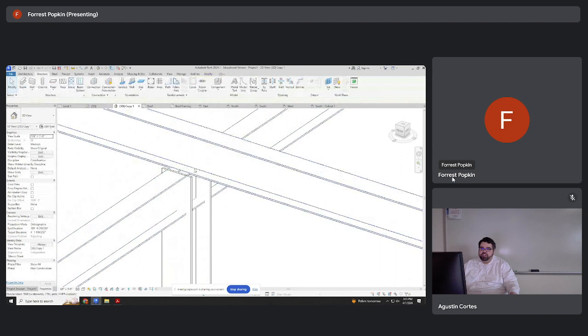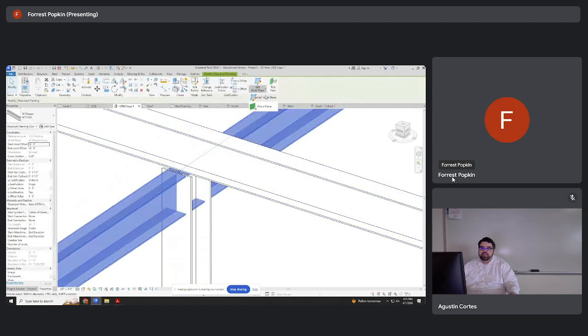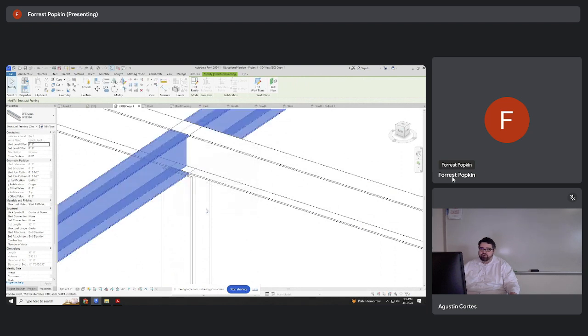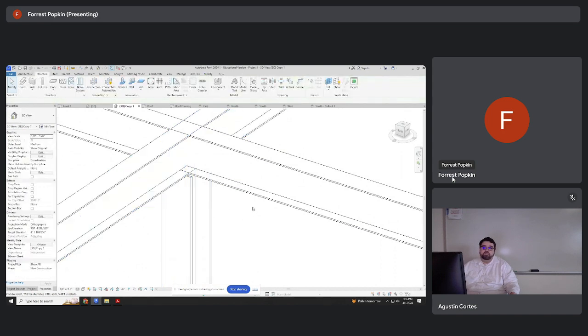Sorry. I go to the top option to edit work plane, and on this menu, it makes it a lot easier because you can just pick a plane, or I can pick a line or whatever. So in this particular instance, you want to pick level roof on the name of the work plane, and it will just put it exactly where you want it to go.